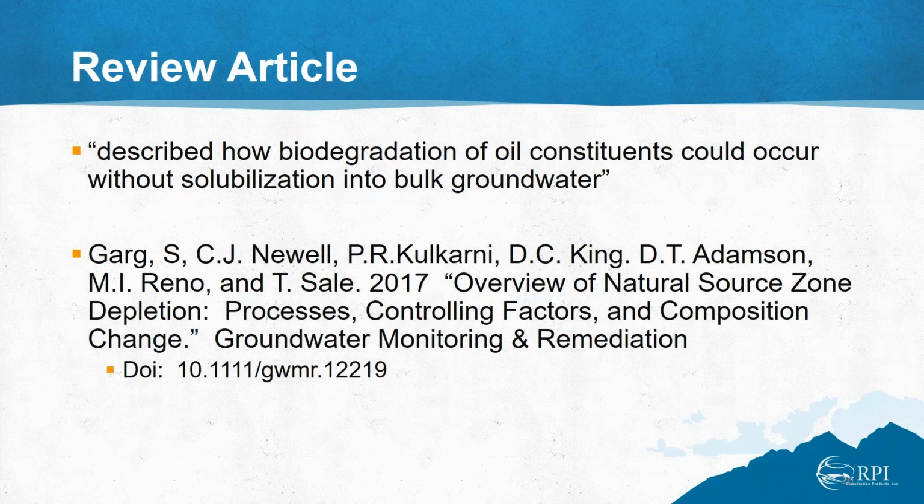We did actually spike enough diesel dissolved in methanol to create about a 50 ppm dissolved diesel concentration in the water, so that we had something that we could measure in the water. So to answer your question, no, there was no free phase diesel that was added to the water. And at least in the short term, we were able to measure a little bit of diesel in the water during the test, but the bacteria pretty well wiped that out early on in the game, and then what was left was just the mass that was on the carbon, which we monitored over time through extraction.